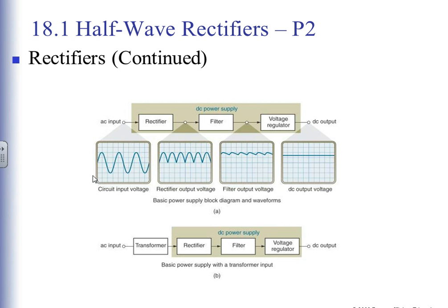All right, so I have some input AC voltage. I'm going to rectify the voltage, and we call this half wave rectification. Well, actually, this is full wave rectification, because I'm rectifying both sides. And then I'm going to filter it. So there's my filter, so that it's almost straight. And then I'm going to regulate it, which gives it a straight line.